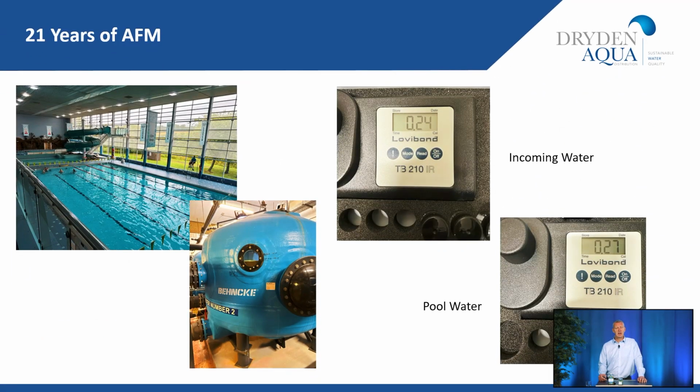Now, bearing in mind this is over 21 years now, the pool water was showing an NTU of 0.27 compared to the incoming water at 0.24. So very, very close to the quality of the incoming water. NTU is the measure of the turbidity, and the maximum acceptable level in the UK is the same as drinking water, which is 0.5. So the higher the number, the more turbid, the more cloudy the water is essentially. So the water today is just as good as it was 21 years ago.